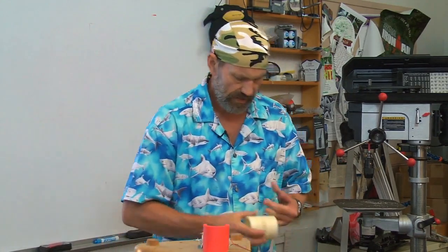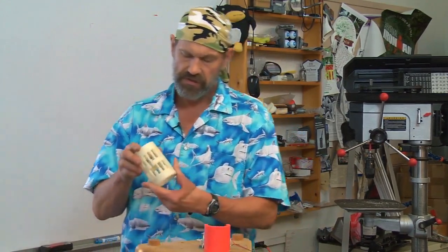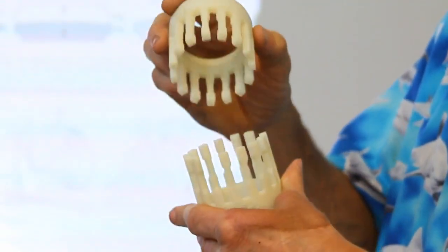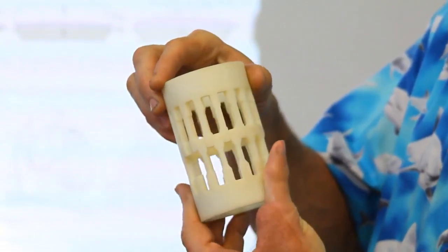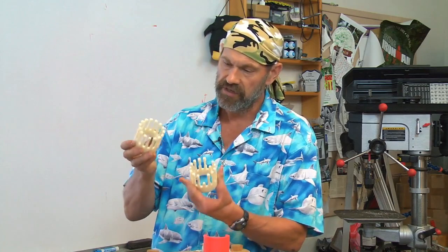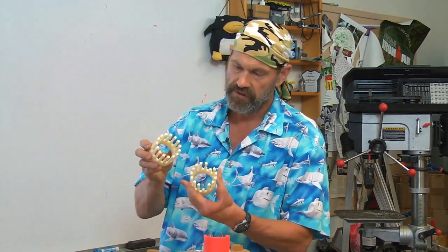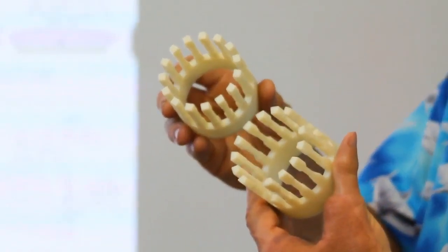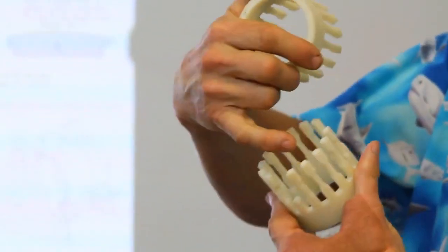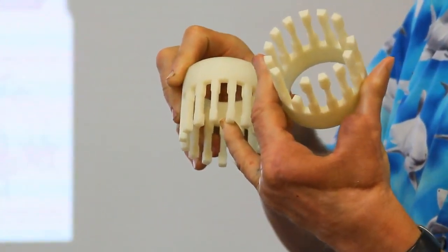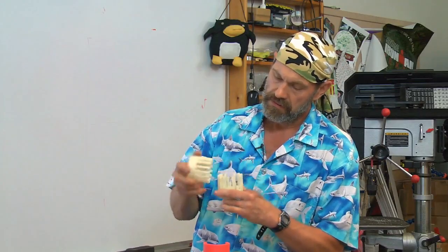And recall, we even talked about this type of joint back in topic 5. Also a coupling. This was a torsional coupling. You have a lot of teeth and a lot of very special features on the teeth where the tapers go, such that the teeth are too big to fit together, but because of the taper angle, when a tooth is forced in between another tooth, it deflects outward a little bit. So you have a lot of teeth, a lot of averaging.